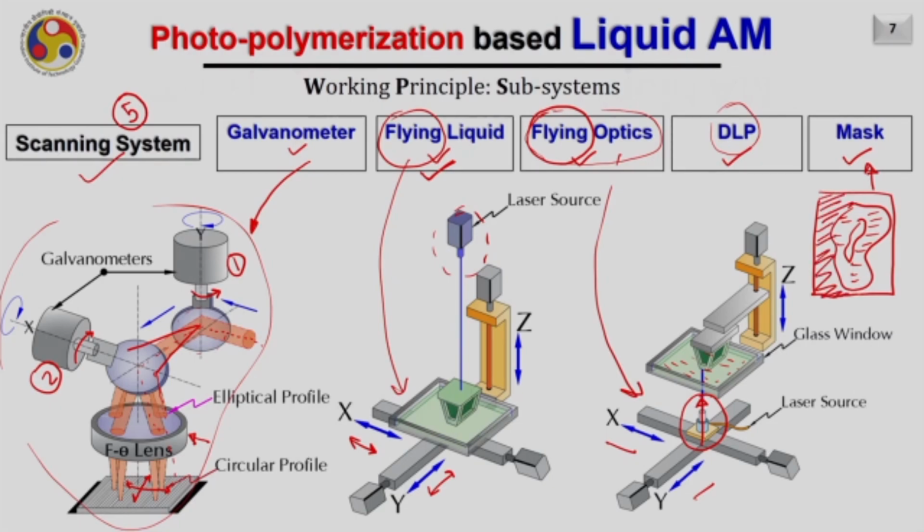This is for example the opaque material, and there will be a transparent material in this zone, and again some opaque material here. So basically a negative of the slicing data will be produced on the mask, and when a floodlight of UV falls, we will just put that mask under this so that the light can pass through only from the appropriate region, and in the region where the light is not required, it will get blocked.